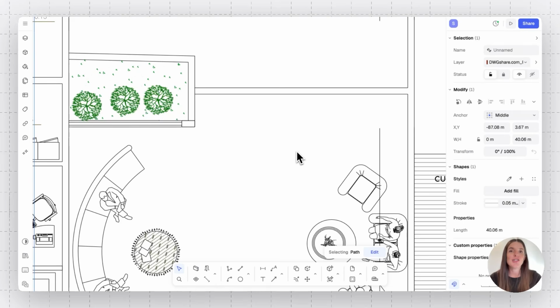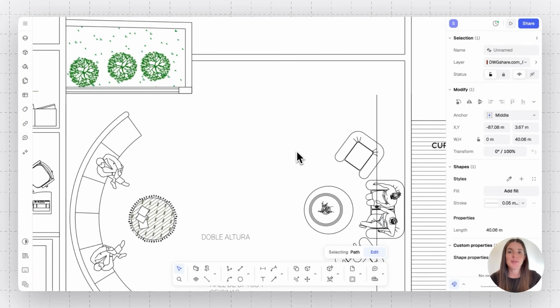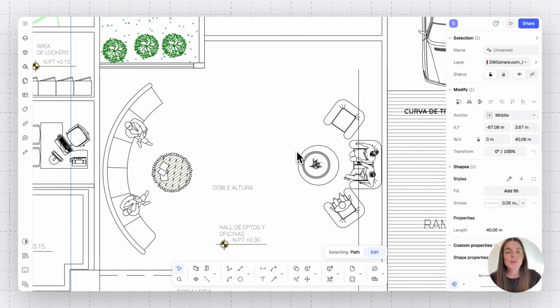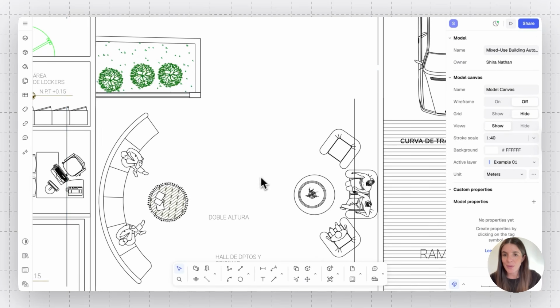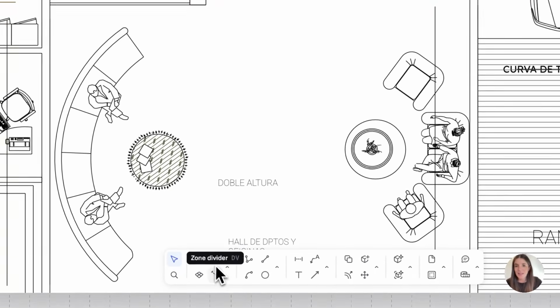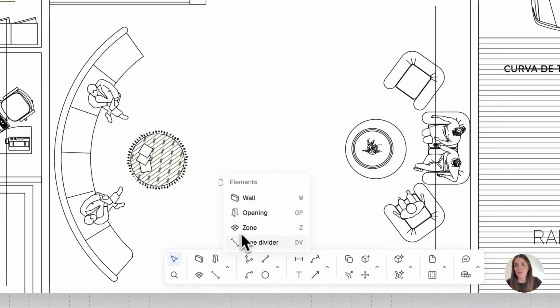And now that we've established that and the fact that you can use the vector lines to draw, I want to also introduce to you the LightBIM features that we have in Rayon to help you draw faster, basically. So you saw how I just drew these walls with 2 lines, either with offsetting or drawing new lines. In Rayon, we also have what we call a wall tool. So let me just quickly delete these lines right here and show you the wall tool down here. Basically, this is the stack of LightBIM tools.